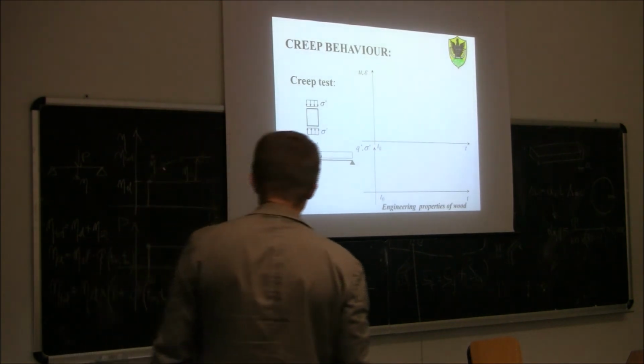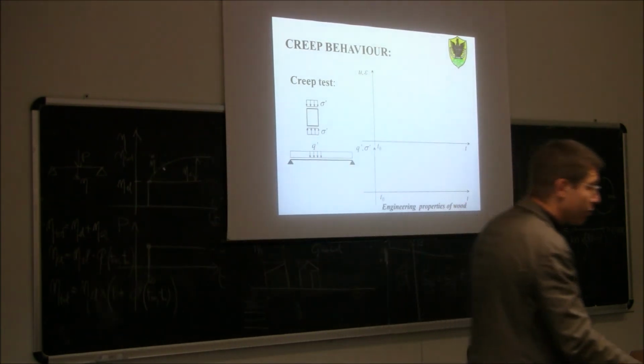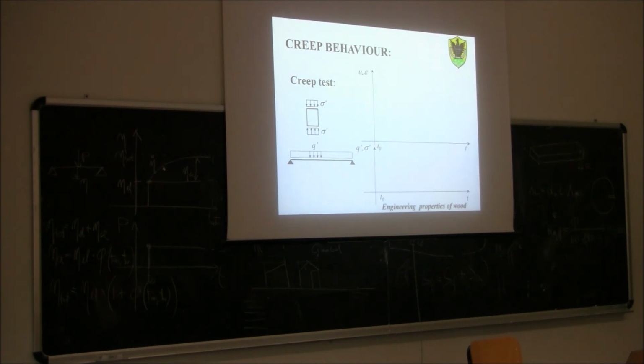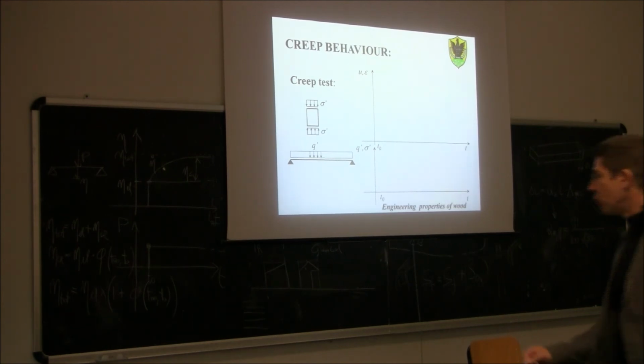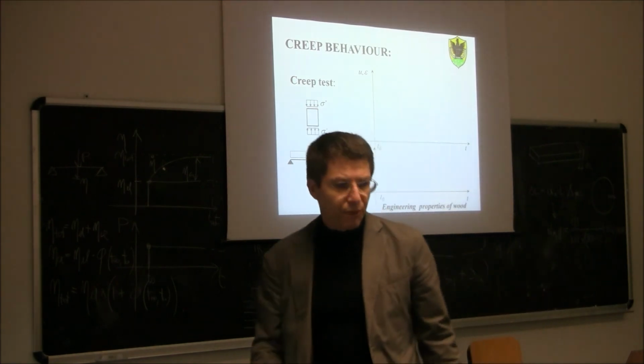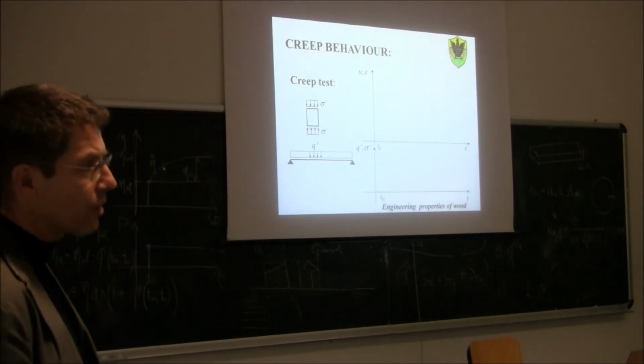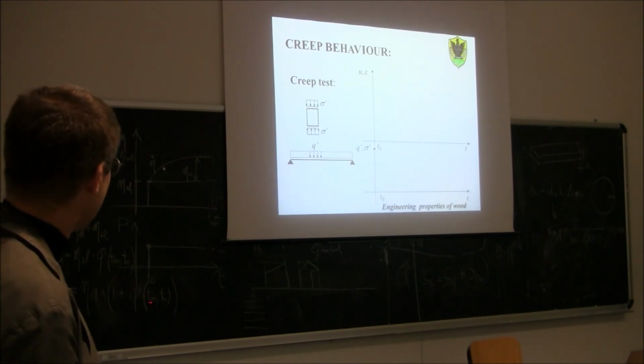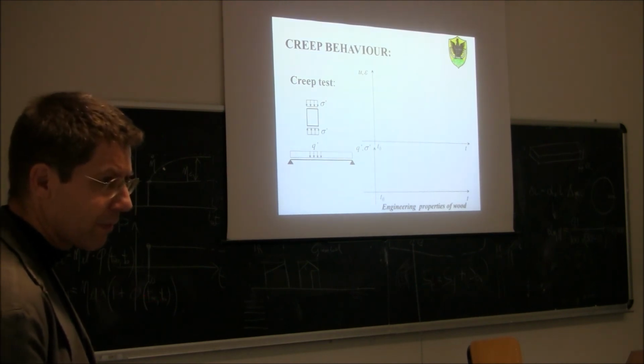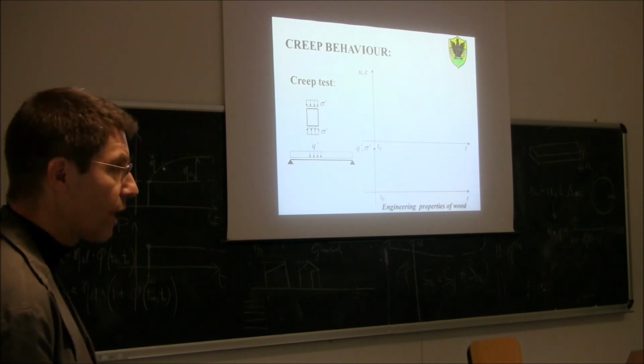So the total deflection at the end of the service life can simply be assessed by calculating the elastic deflection and multiplying it by 1 plus the creep coefficient. The creep coefficient is provided by the regulation. So there are some formulas to calculate phi of T infinite, T0.